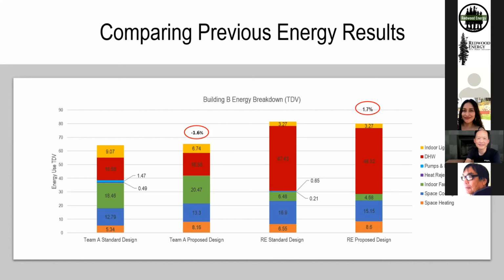You can do settings within the software that are important, but are not visible in the printouts and cannot be plan checked, even though they're important. And this is an example of that, where you can disappear square footage and have it be difficult to note, and have it change the whole model of what's important to do. If you have a different amount of TDV energy allocated to HVAC because you've disappeared square footage, then the domestic hot water system might look more significant than it actually is.